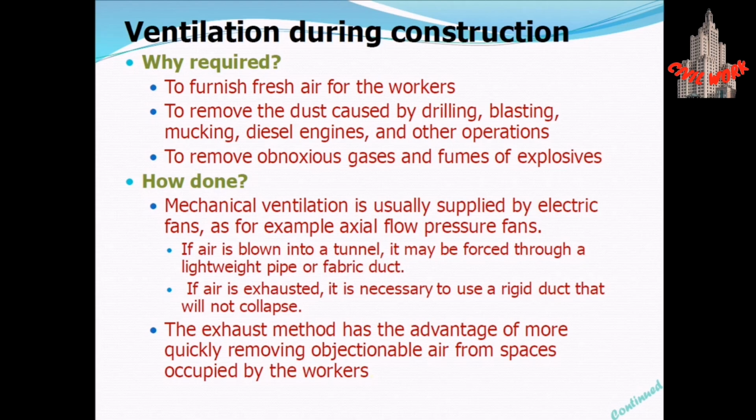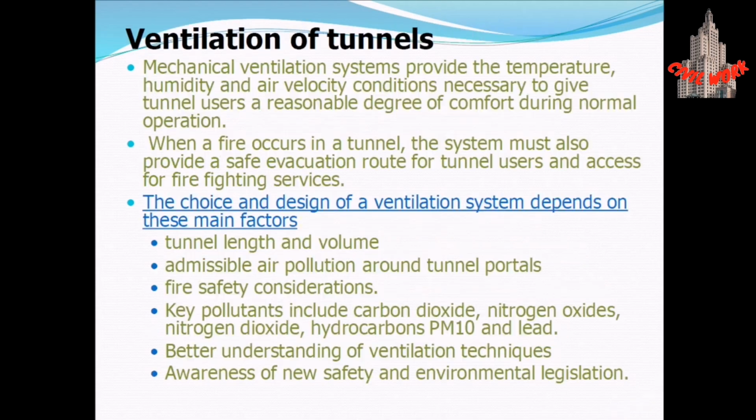Ventilation during construction is crucial to remove dust, fumes, and other airborne contaminants, ensuring a safe working environment for workers. In tunnel construction, ventilation systems are designed to remove dust and debris, to control air quality, regulate temperature and humidity, and to provide fresh air.